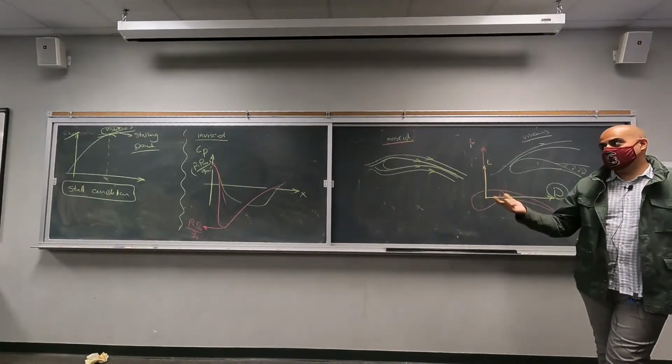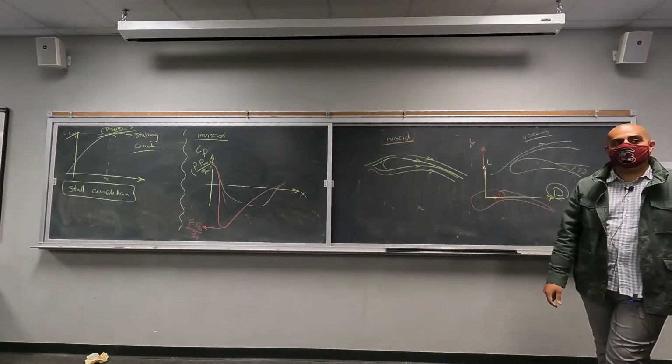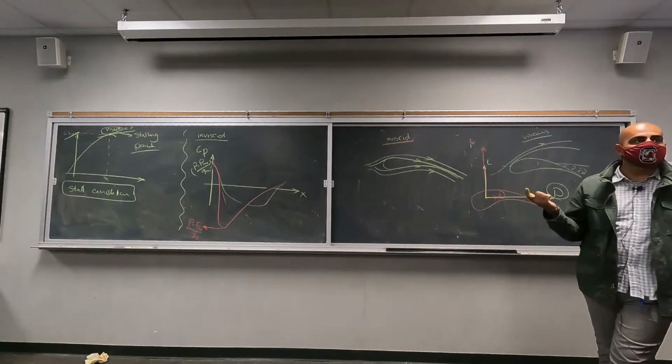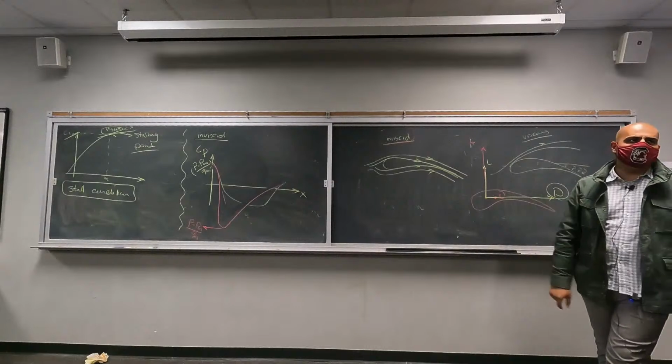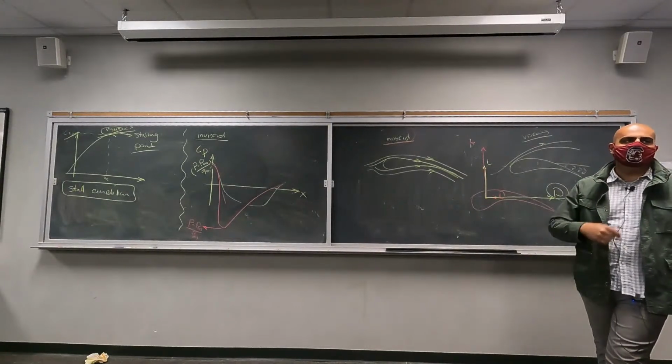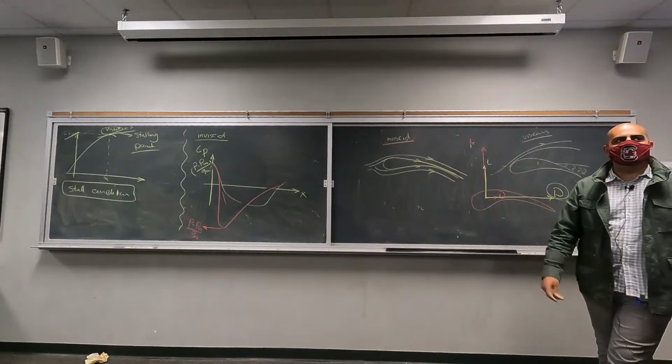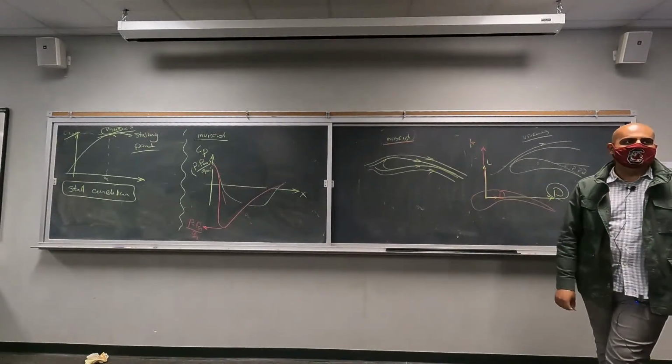And it's very difficult, at a very high angle of attack, when you have surpassed the stall conditions, running this type of simulation is very problematic. It will diverge. You have to make a lot of assumptions, help the solver a lot, and do a lot of relaxation. So yeah.